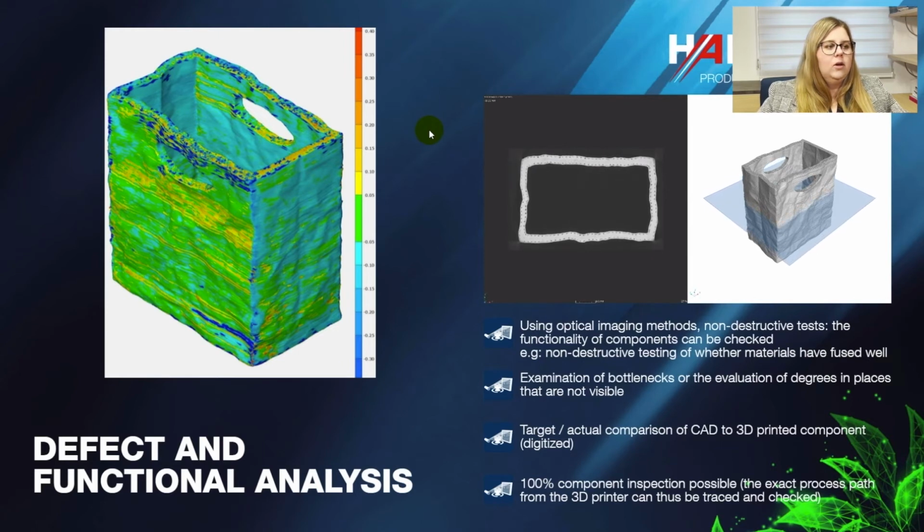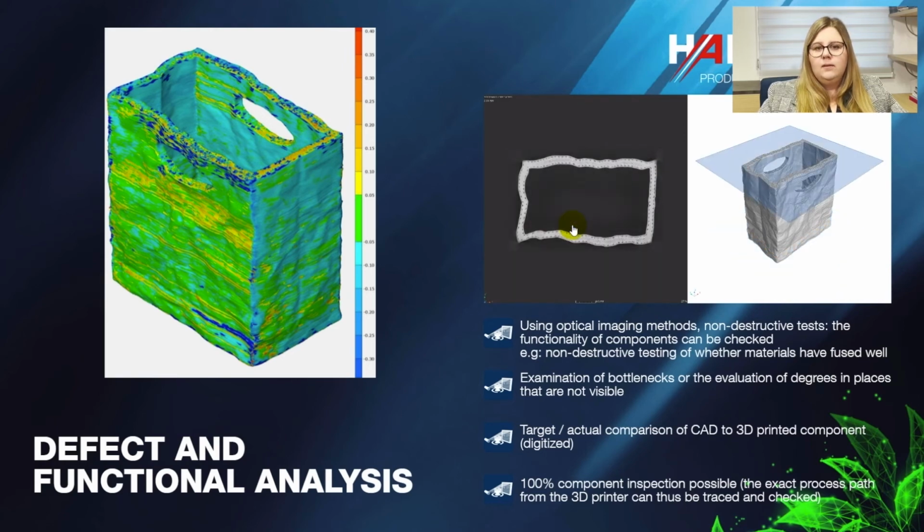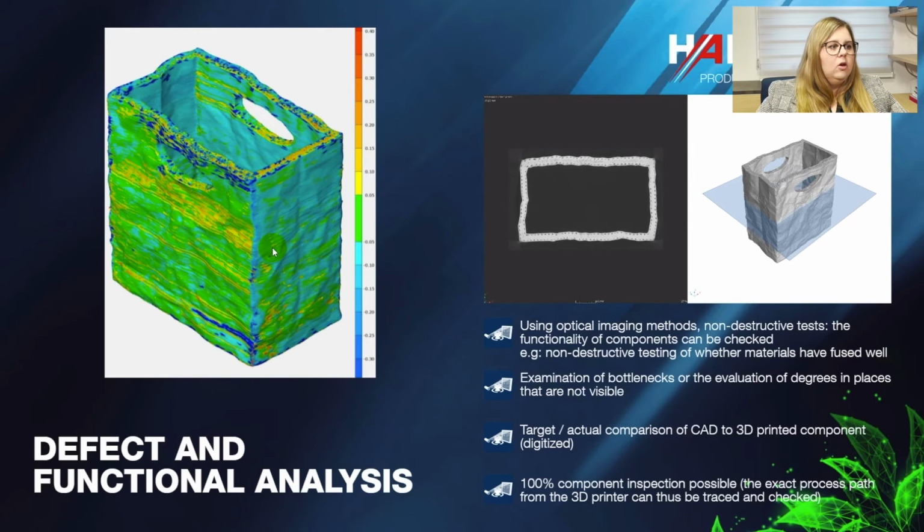This is the example of our crumple bag. This is a part that is plastic printed. This is actually reverse engineering, because we took an actual bag which we crumpled and then digitalized. We use different manipulation programs in order to increase wall thickness and create a CAD model. It was then minimized because the actual bag was a little larger than what we have here, and then it was digitalized and printed by our plastic printer.